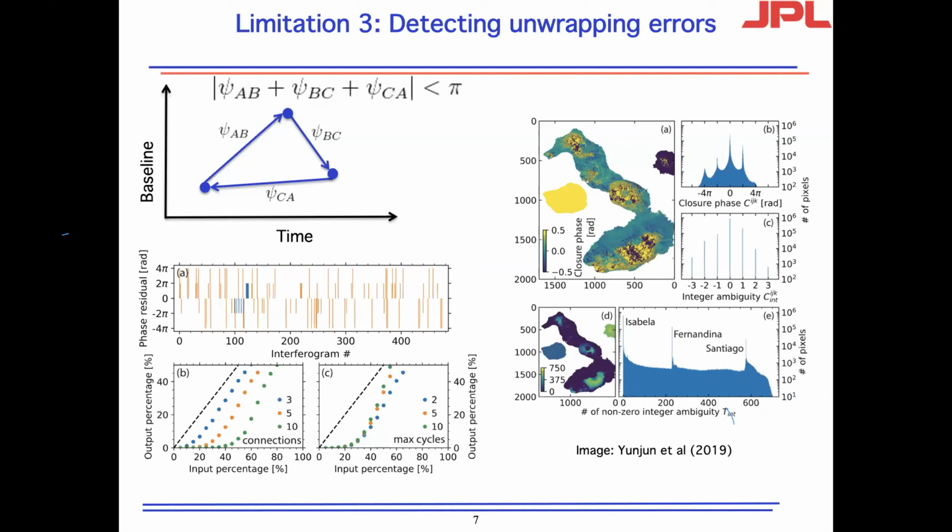Let's say here in this one, I used around 500 interferograms, which can form around 900 interferogram triplets. And if we check the integer number of all those 900 triplets, we can sum them up together into subplot D. And that's why you can see in D here that the big island is very dark, almost 0, while the 2 islands on the 2 sides are non-zero.